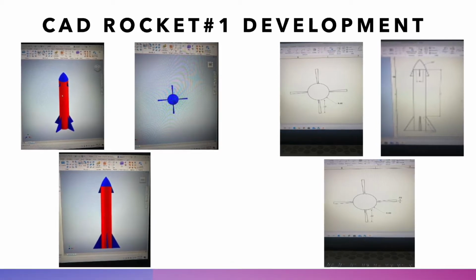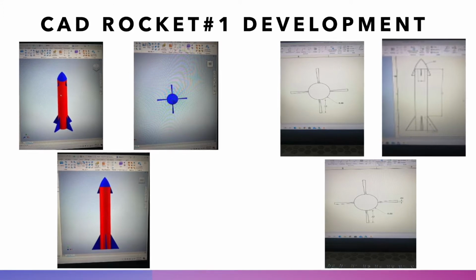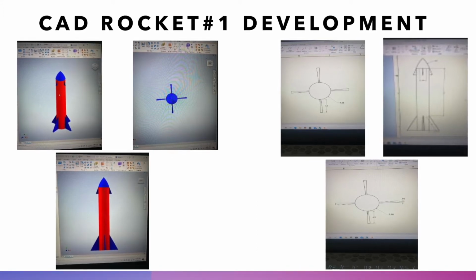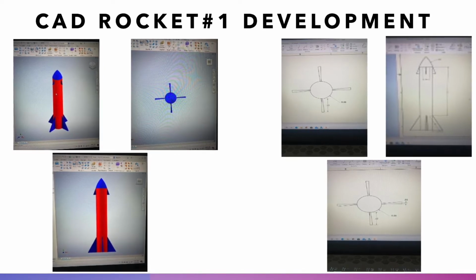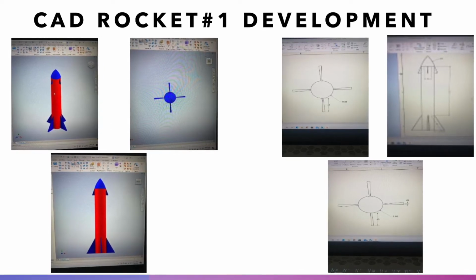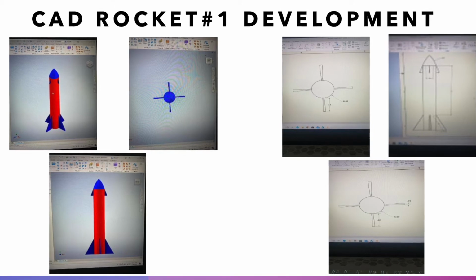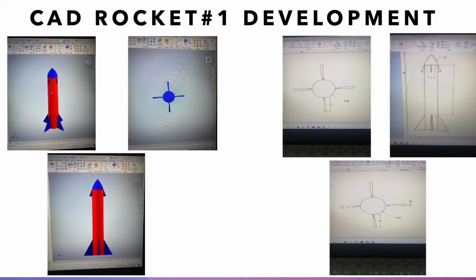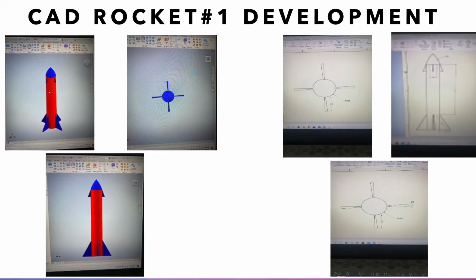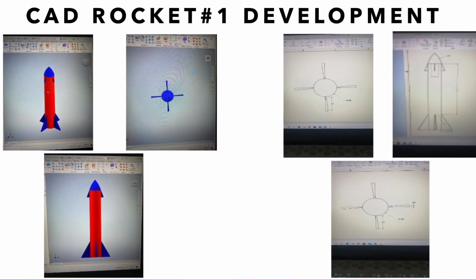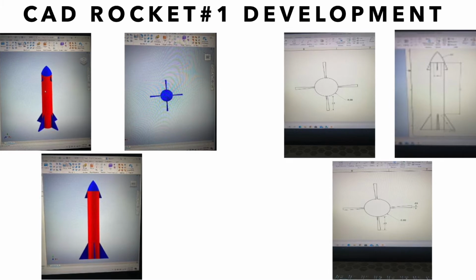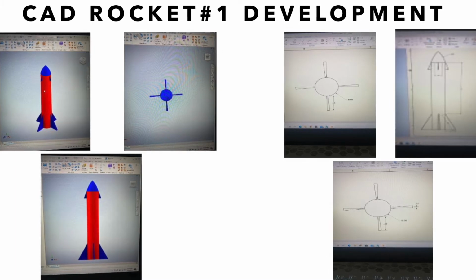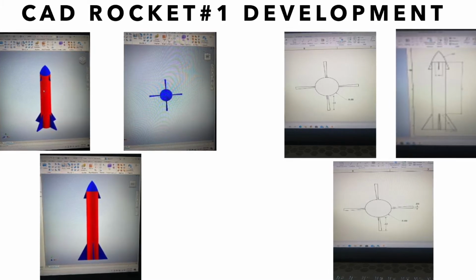1. Select the Start 2D Sketch option followed by the Emboss option to start the rocket body. 2. The next thing is to select Dimension, and the desired dimension is placed and adjusted. When finished, press the Finish key. 3. Then click on the Revolve option and arrange the cylinder in the upper part of the rocket. In the upper part, add one more line with the Line key, then select the Arc option where the desired angle is given from the upper point of the last line towards the first part of the rocket's body. To conclude this step, click on Finish again.